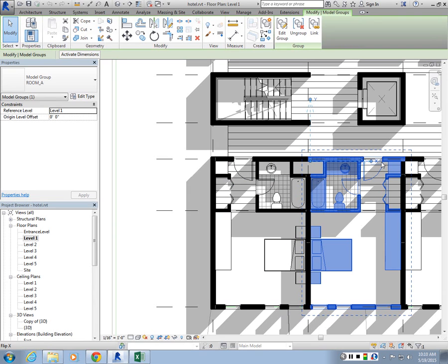So sometimes when you make a copy of the group and you want to rename it as something else so that you can create variations, by default, this will be set in the center of the group. And what you have to do is relocate it at the corner and mirror it so that when you make copies of it and you change the groups, they actually do change in a complementary fashion. Their origins are set the right way.